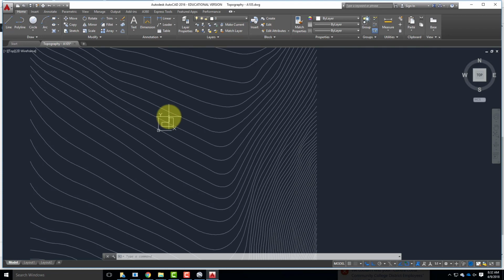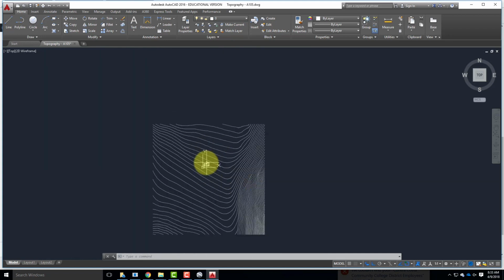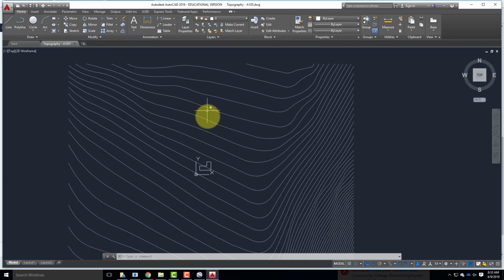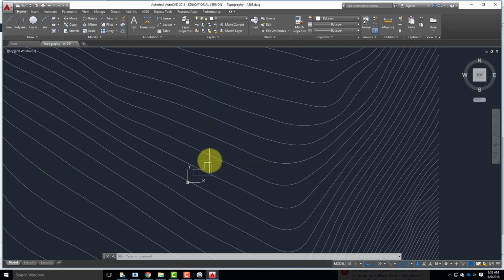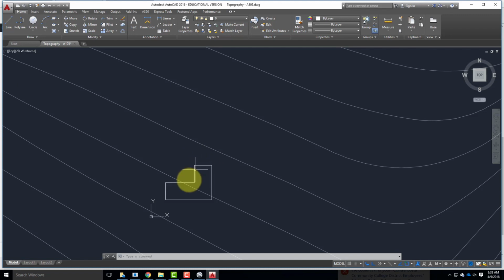So your job today is to actually start designing, to start thinking about these spaces that are written out in part 1. Remember, your views of the canyon, your downslope views are out this direction. North is up. North is straight up in this view. So windows on this side or this side of your building are generally tall. They're going to have your big windows. You're not getting a big solar heat gain. So that's a good place to start.